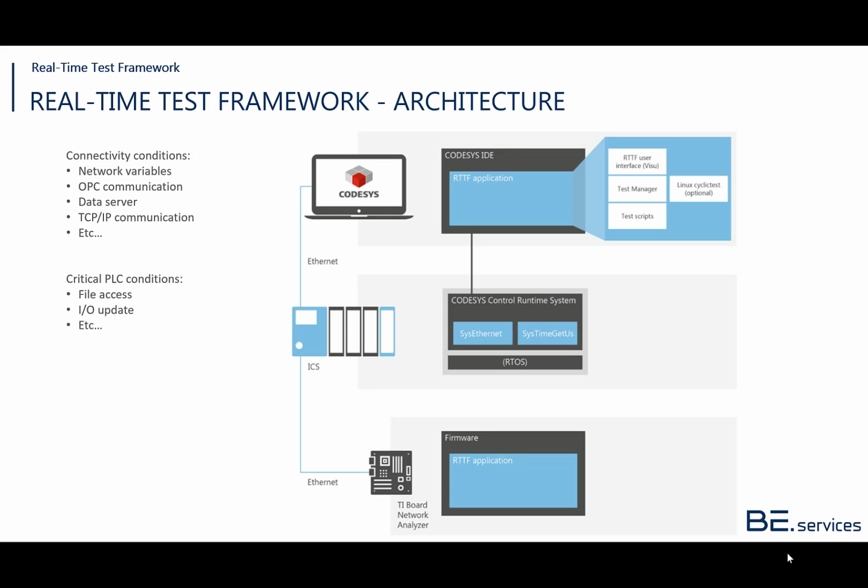On the IDE side, RTTF is a package comprising a user interface, a program, libraries, test scripts, and even integrates the Linux cyclic test should the device be based on Linux. The execution is either done manually or using the CODESYS Test Manager as automatic testing environment. The third part of the system is a specific board from Texas Instruments that will replace physical I/Os and for which a specific firmware has been written.